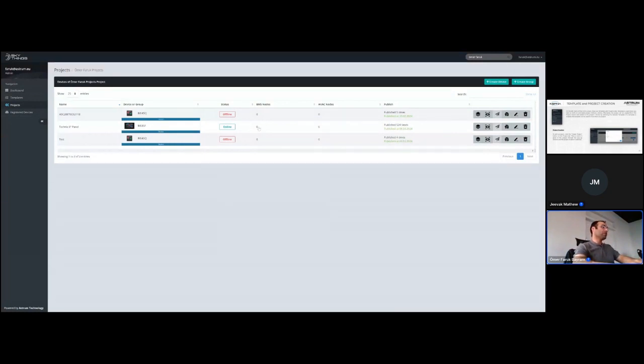To put it simply in KNX terms, if you have 500 group addresses in a KNX project, you will see this count here. If you reach this number, you will not be able to publish this project to your device, so you need to increase this license.